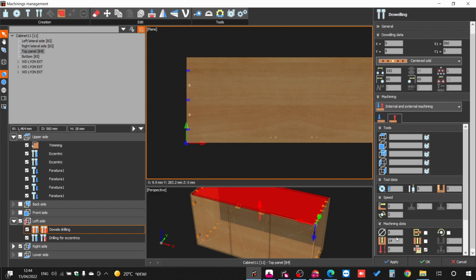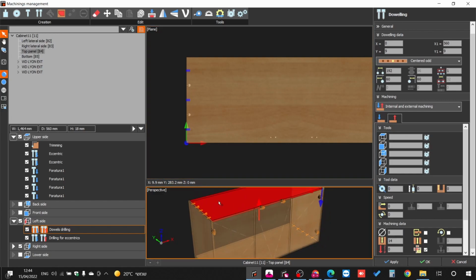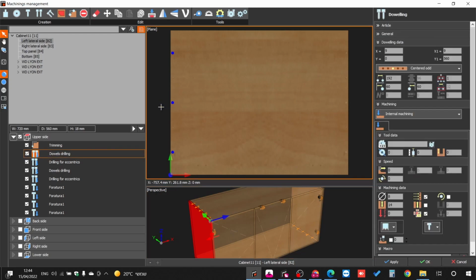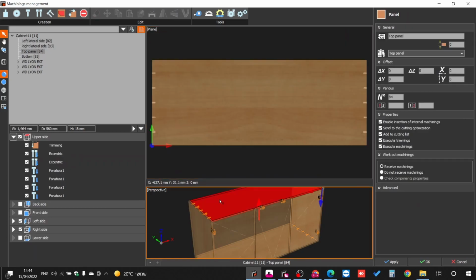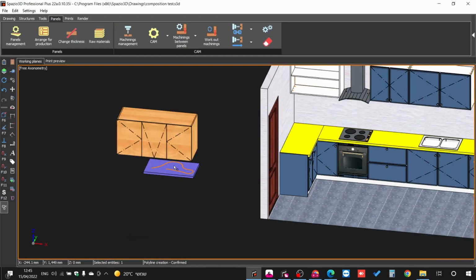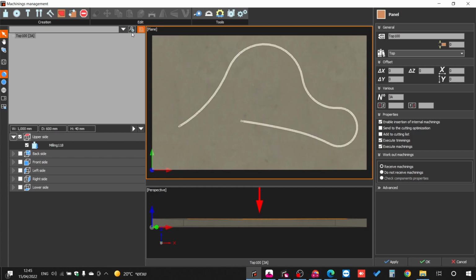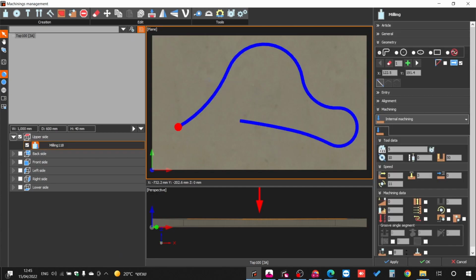And we are going to export a 14 millimeters machining in here. In fact, when we select this, you see that it has this option, elaboration made from machining transfer. So it means that this machining is here only because this element received an external machining from another tool, from another hole, okay? So from here, we can decide if this is an internal machining, external, or both of them.